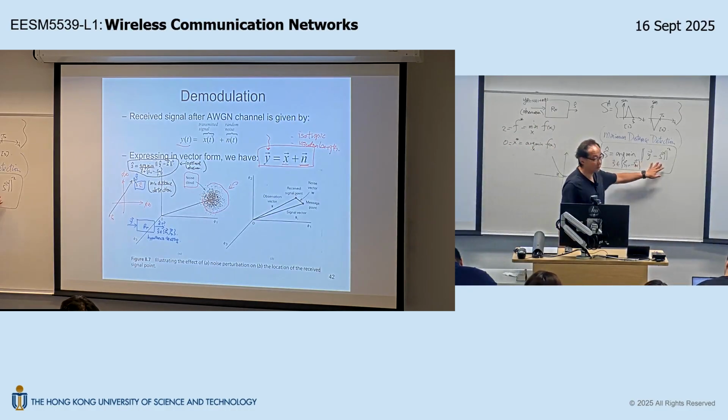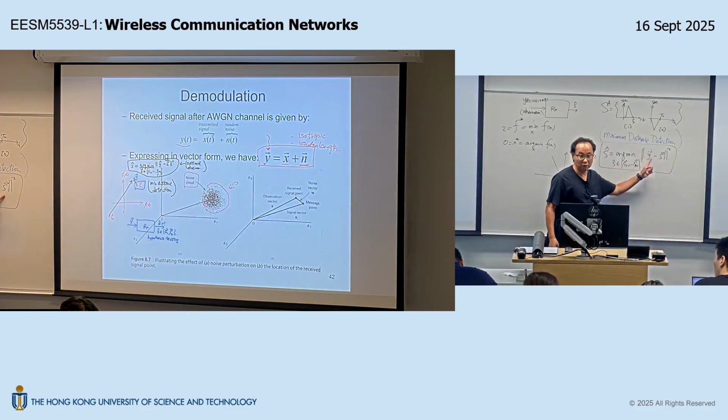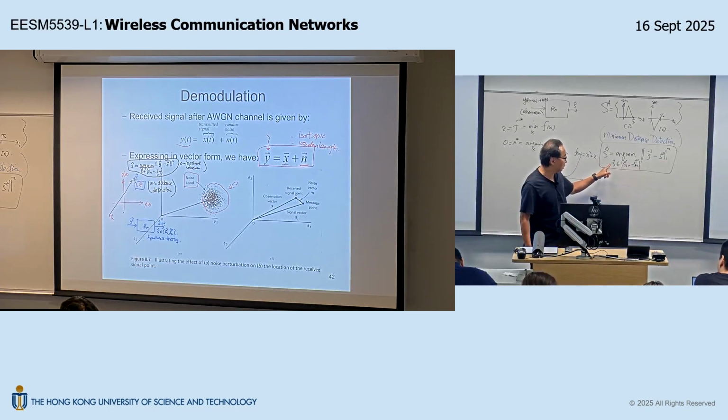We are solving a minimization problem. Our objective function, our f(x), is now the distance between the observation and the hypothesis. Now, the hypothesis cannot take any value. The hypothesis S can only take one of these M values, right? Because that's the design of the M-ary modulator. The transmitter symbol cannot be arbitrary. The transmitter symbol can only be one of the members of the signal set, right?